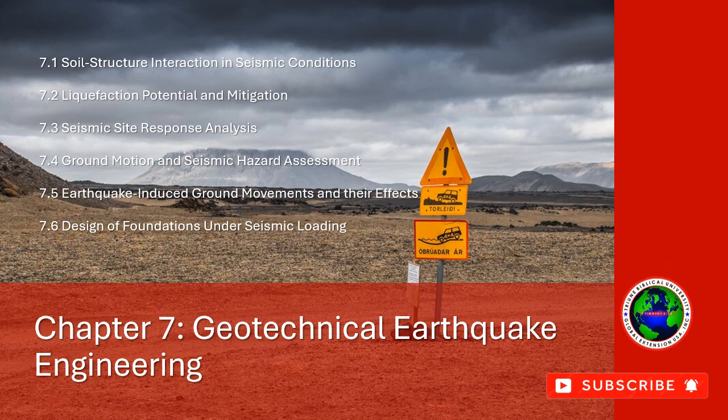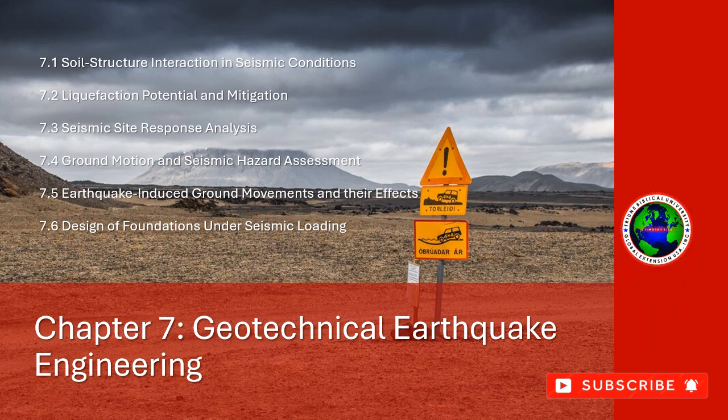2. Probabilistic Seismic Hazard Analysis (PSHA). PSHA is the most common method for evaluating seismic hazards. It combines the likelihood of different earthquake scenarios in terms of magnitude, distance, and fault characteristics with the expected ground motion at a site.